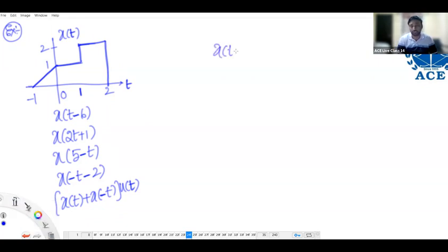First signal graph we are expecting is x of t minus 6 with t naught positive. t naught positive means what, sir? Directly right shift of 6 units to the existing time axis.